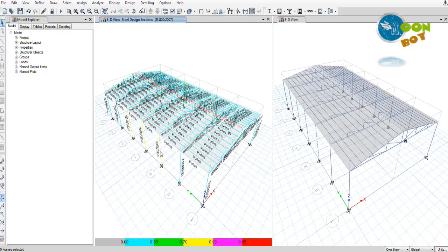Then these columns are safe. So these columns are taking heavy loads. That's why point bracings are required apart from the program defined bracings. The program defined bracings are at the end, that is at the top and at the bottom, but we have provided point bracings for these columns at 0.25, 0.5 and 0.75 distances, that is the relative distance.